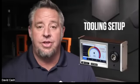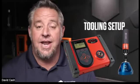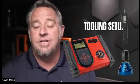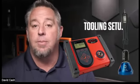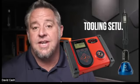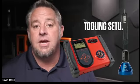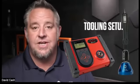And so in this case, we want to use an analyzer that would be one analyzer that has a built-in transducer with the ability to capture that data. Or it could be an analyzer like this that also has a built-in sensor or the ability to add additional sensors to it. And that can be used, again, to set up hand tools or even a power tool. In this case, we would be using a rundown or joint simulator to be able to set that power tool up. But this type of analyzer, we can add different types of sensors to that.